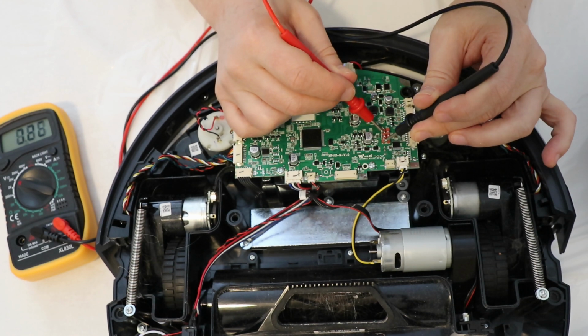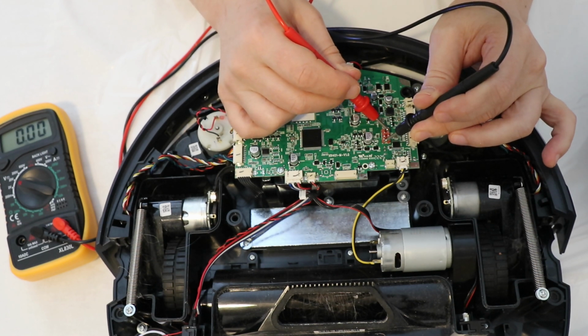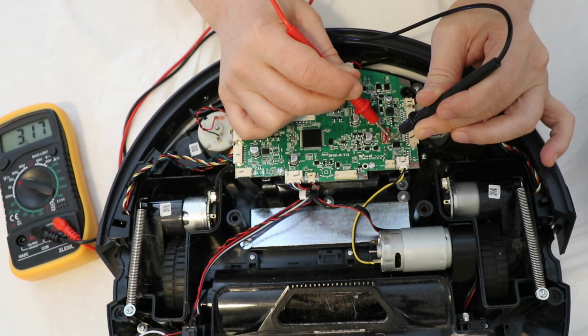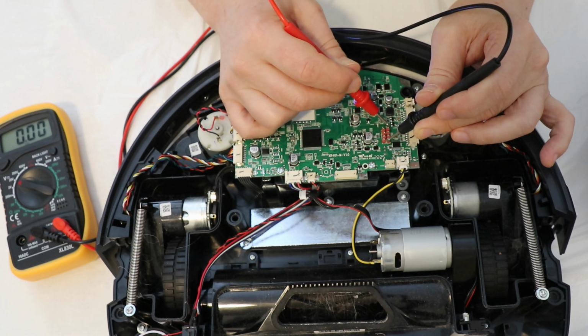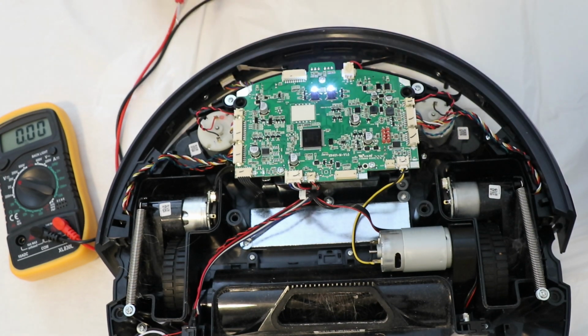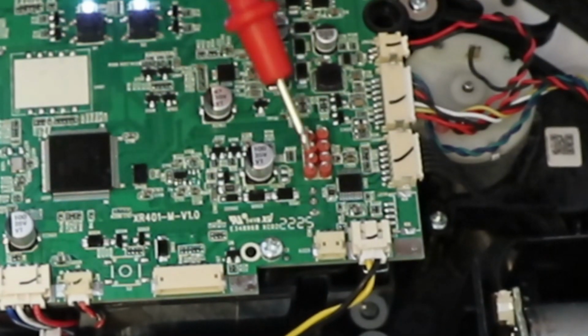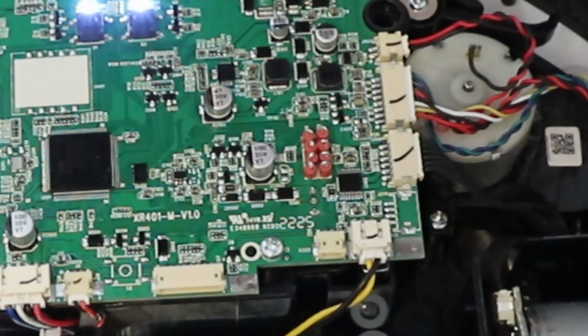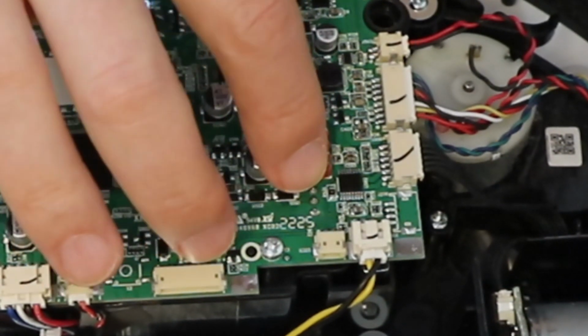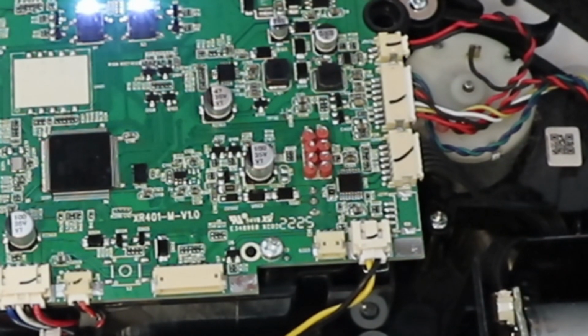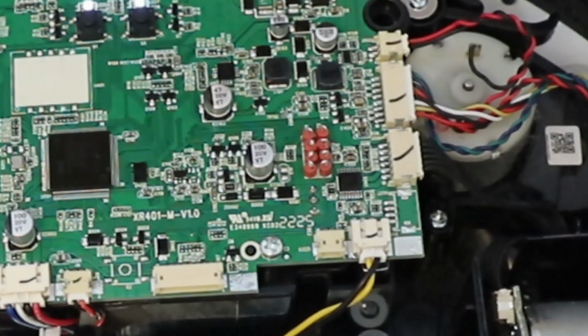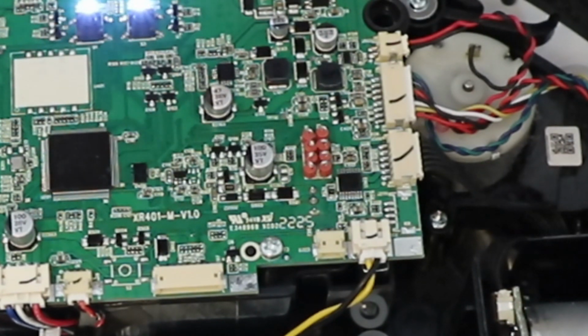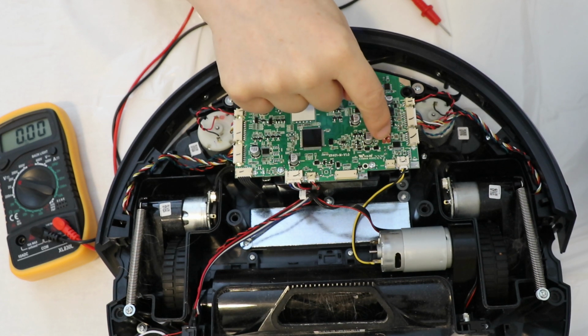That one's also 3.3, and that one's also 3.3. Okay, this one is showing 3.3 roughly. That's showing 0. That's showing 3.3. So if I had to guess, my guess would be that the UART is this row, because typically the transmit pin, when it's idle, is held high, so we'd expect to see 3.3 volts. And the receive pin probably has a pull-up resistor pulling it up to 3.3 volts. So my guess is this inner one is the UART.